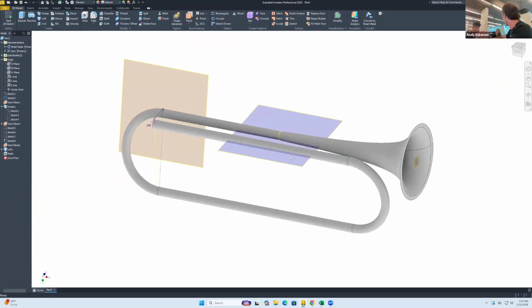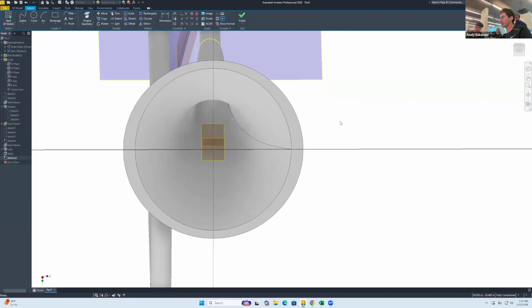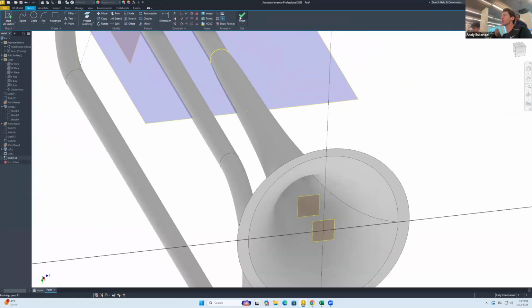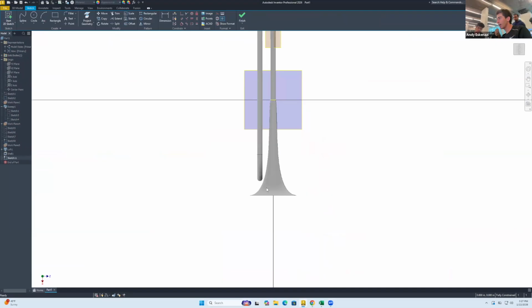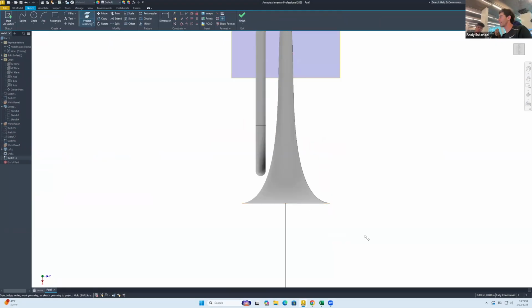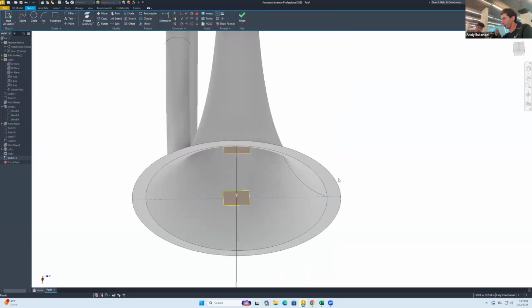So this, we're not done, but this is the step that we can start trying out right now. If you want to go, one last thing, this is more like Andy being particularly fancy, but you guys don't have to do this. I'm gonna do a little line from, actually no, this is not the sketch I wanna work from. Let me delete. I wanna work from this sketch. And I want to project geometry that line. And then you see how I'm selecting the circumference, but it becomes a line. I'll make that a construction. Let me do a little circle.